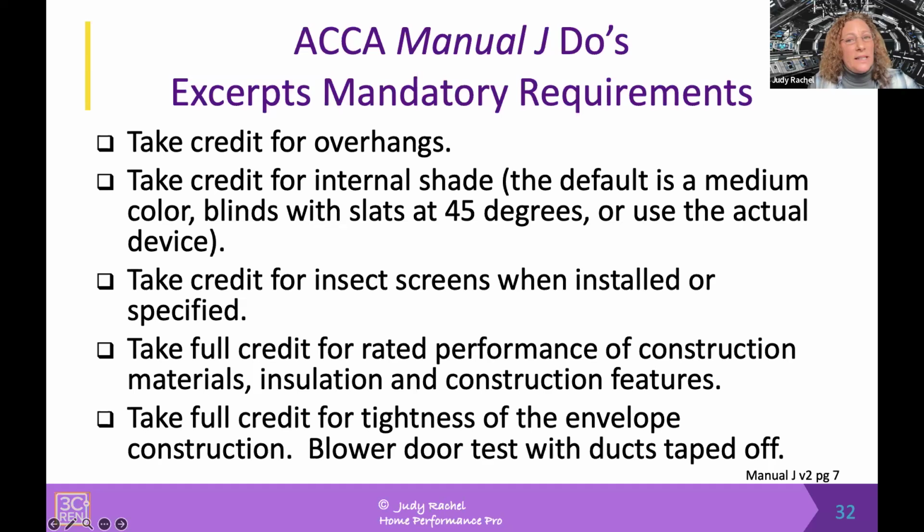Now, the blower door test is interesting for the load calculation procedure in that when we typically do a blower door test, say, for an energy audit, we don't tape off the duct system. We include the duct leakage in the total enclosure leakage. But in the load calculation procedures, duct leakage is quantified in a different way in a different place in the procedures.